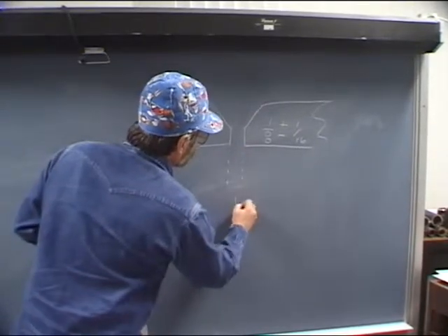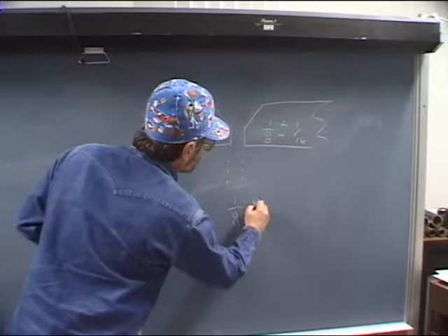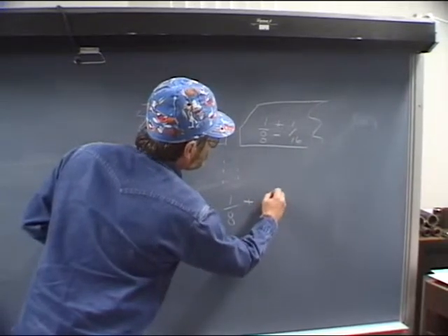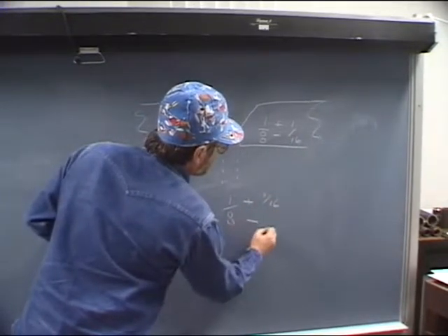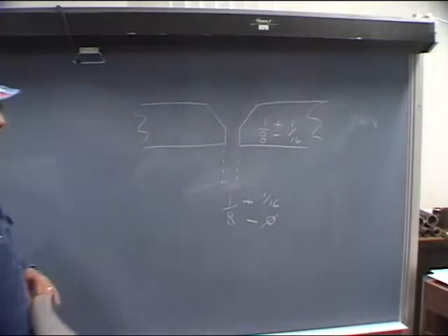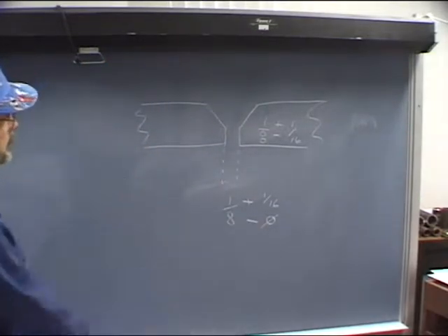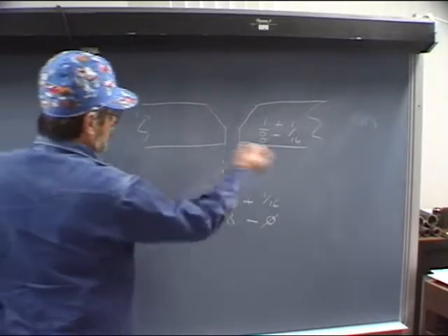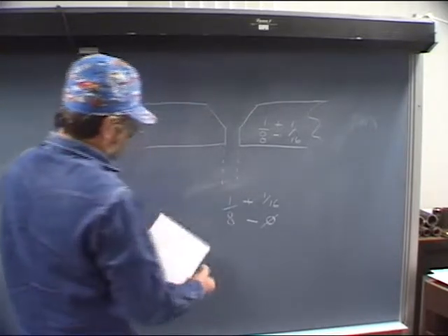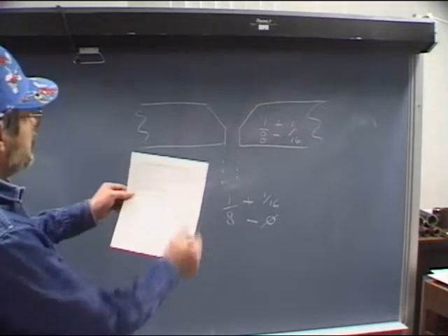Same thing here on the root opening. We might say 1/8 of an inch plus 1/16 minus 0 if we wanted to. So he can go a little bit bigger, but he can't go any smaller. So we're establishing ranges that they could do it with. And those details then would be added here.